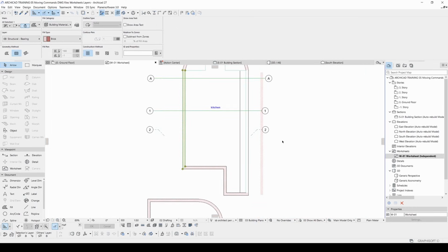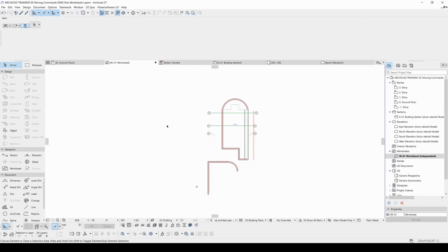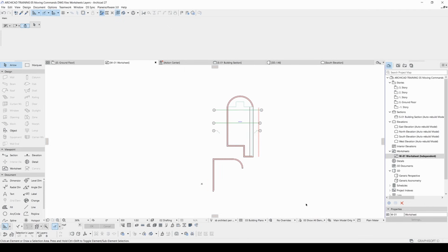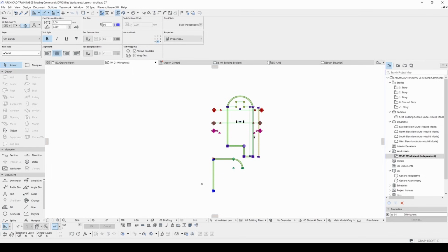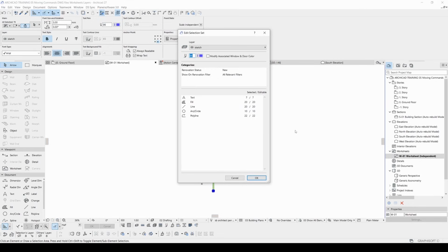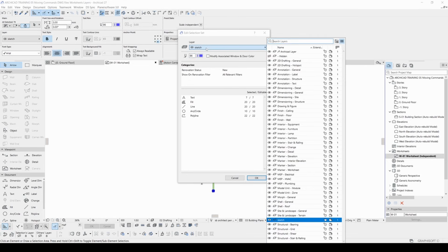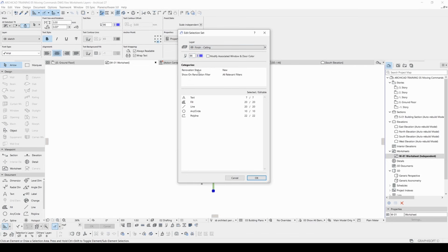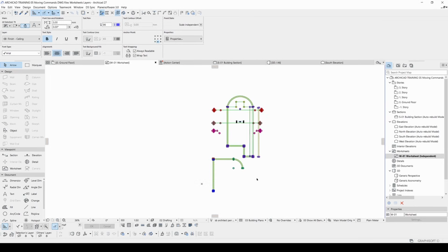This is structural bearing. Well, to do it, I will show you the tip of the day. You will select all of the elements you want to change their layer. After that, do not forget this. Hit Ctrl plus Shift plus T. Ctrl Shift T. And then you will see the layer sketch. You will change this. Something different. You will click OK.